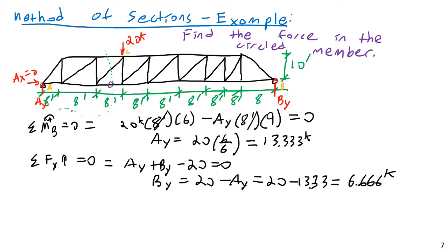Right like this. I'm just going to cut out the left end of the truss, and that's going to cut through 3 members, and in turn that's going to reveal 3 member forces. So I'm going to have these forces here, here, and here, and those 3 member forces will be revealed, and then I also have my reactions.